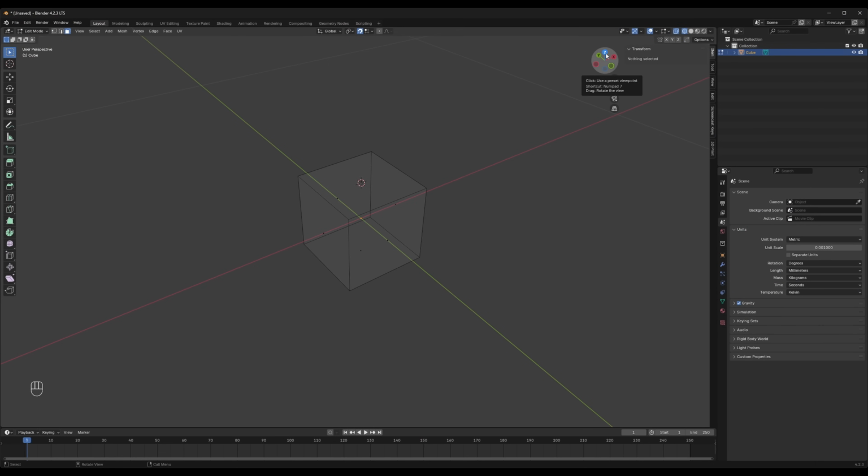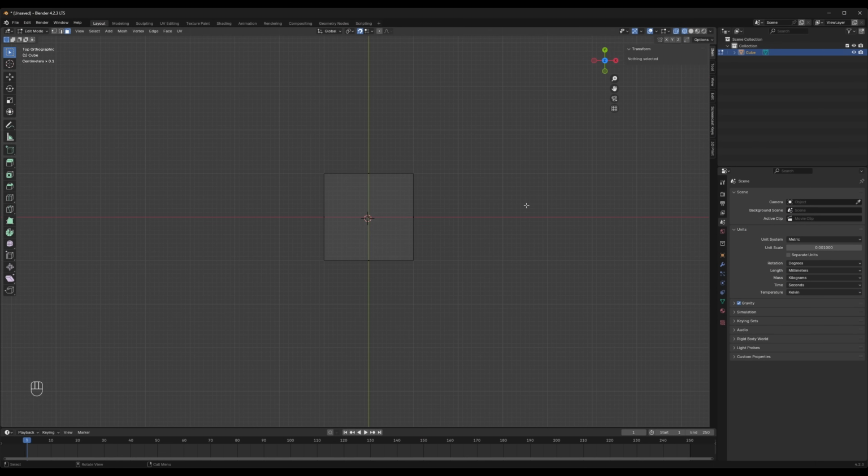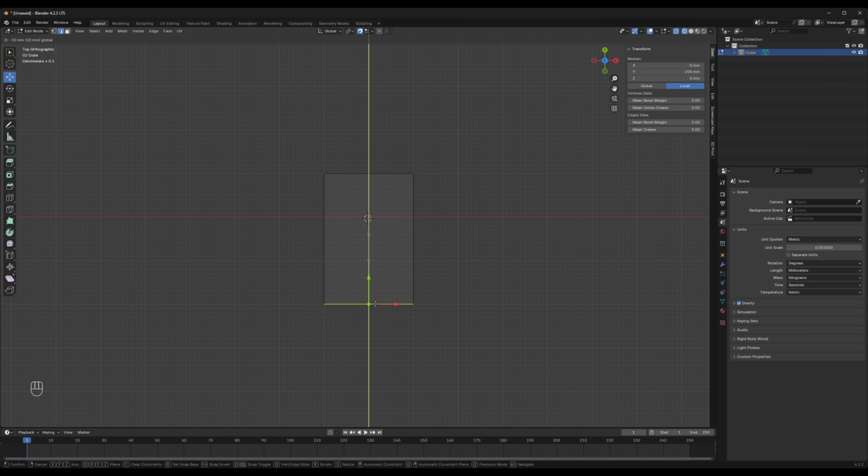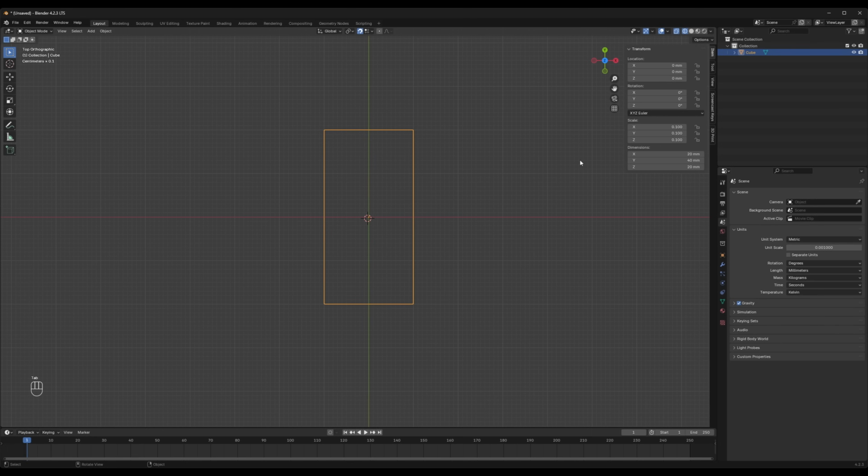So we'll go back into our top Z for orthographic view and adjust this with our edges. So we want to pull off 40 millimeters or 4 centimeters. And the way we do this, again, with our grid is we're using these highlighted lines which say we're in centimeters right here. So we can move this and then click our cursor up here for move. And we'll drag this along the grid until we're at 40 millimeters. Then we can tab back to edit and see that our cube has changed on the y-axis for 40 millimeters.